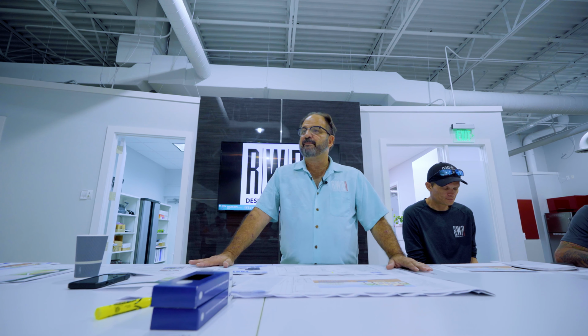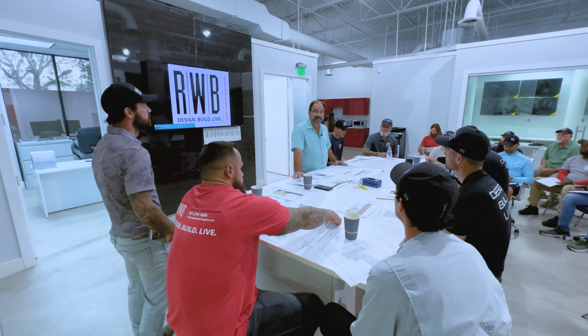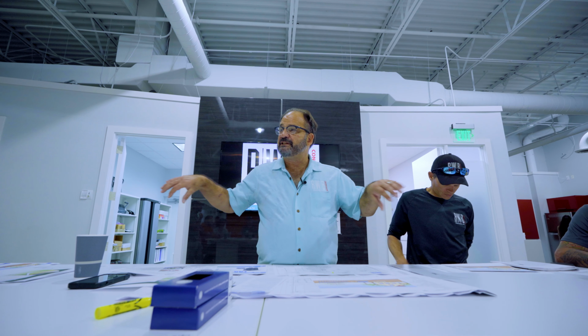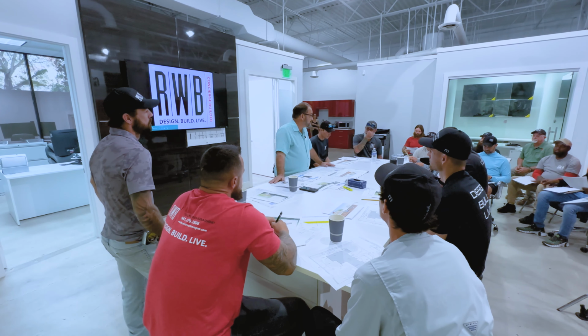If you have a property that has a well, this obviously is an issue because you don't want this too close to your well. So there are restrictions as far as how far these can be apart. If you have a well, sometimes it's 100 feet, sometimes it's 75 feet, because you don't want what's coming out of this going down into the water system and then being pumped into your drinking water.